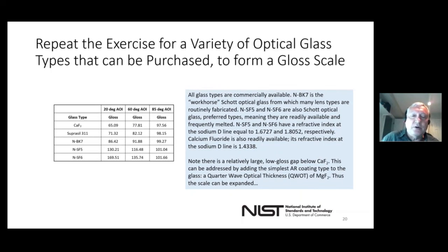It may not be important if you're measuring strictly specular samples, but it's very important if samples having a diffuse component are being measured. And in those cases, some of the reflected light is diverted away from the detector because it's scattered away from the receiver. So that would lower the measured gloss value. So it would be very helpful to fill in the gloss scale with values much less than those associated with the specular.